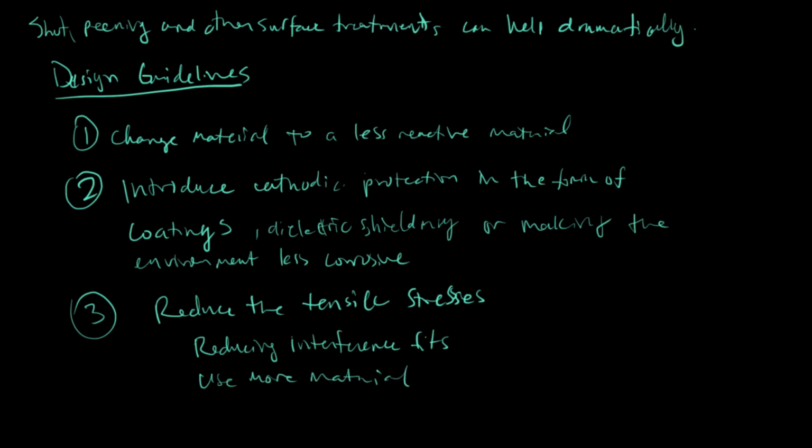For example, you have material that experiences load. Well, distribute the stress through this cross section. By adding a little bit more material, that load is distributed over a larger area, reducing the tensile load. You can also anneal the material, or you can do shock heating of the surface.